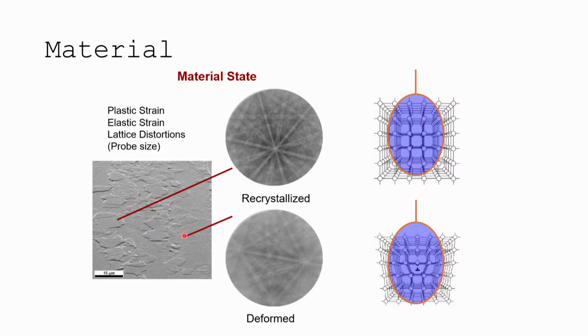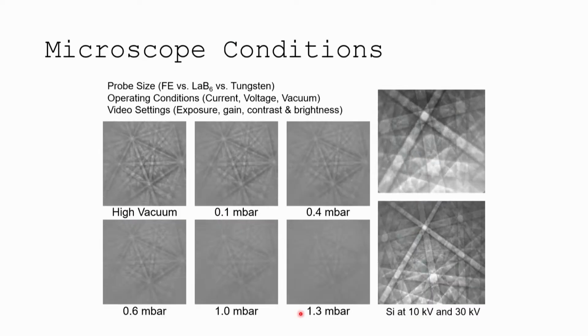It's just looking at two different parts of the crystal. Just that this one stayed deformed, this one's recrystallized. And this deformed one, since this is recrystallized next to it, this is also probably pretty well recovered, so it's not even as bad as it would be if it hadn't been recovered already, right? All right, so that's the first thing, whether we have deformation in the lattice or not.